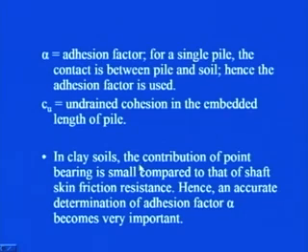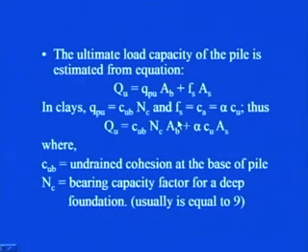In clay soils, the contribution of point bearing is small compared to that of shaft skin friction resistance. Hence, an accurate determination of adhesion factor becomes very important. You see, this part is quite negligible in case of piles in clay, because most of the load coming from the superstructure to the pile is being mobilized through this particular term.